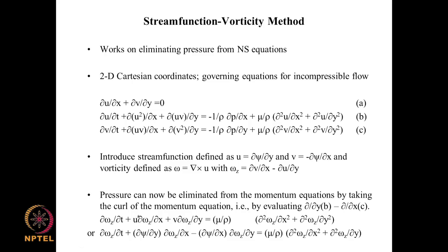with this. Here we are trying to eliminate p, and we can completely eliminate u by substituting this definition for u and this definition for v. Once we do that, we get this equation here. So, in this equation we see there is no u, there is no v, there is no p, and it is obtained from rewriting the momentum equations, and we also make use of the continuity equation to come up to this.